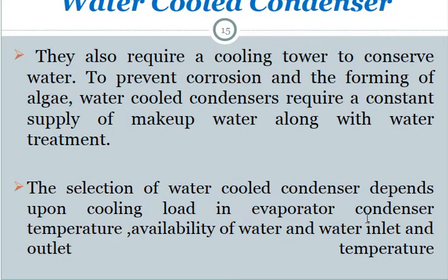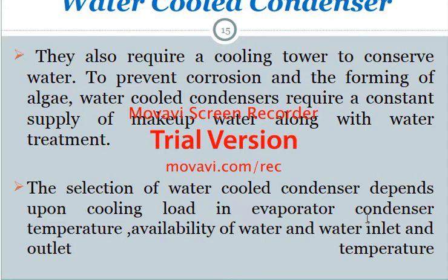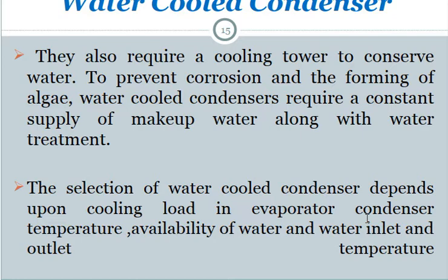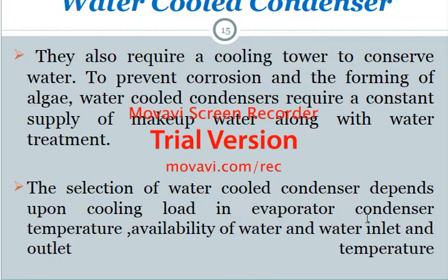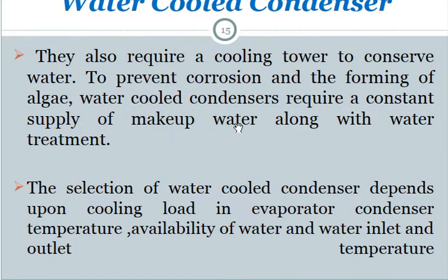They also require a cooling tower to conserve water, to prevent corrosion and the forming of algae. Water cooled condensers require a constant supply of makeup water along with water treatment. As we know, when you utilize water, of course, it will invite algae. So water with algae cannot be sprayed, right? So we need regular service to clean the algae.